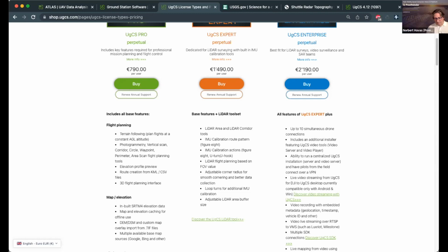Well, if you have a camera which is able to capture this high resolution, then it's possible. It depends a little bit on the crop, but for the usual crops, we can go down to 1 millimeter per pixel GSD, and with a P1 camera, probably with the teleobjective, you can fly around 60 to 80 meters and still get data which is suitable for this use case.